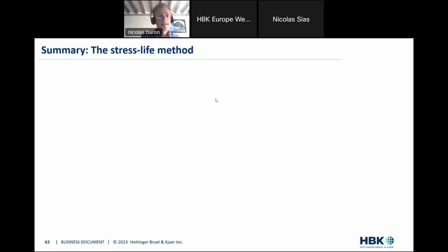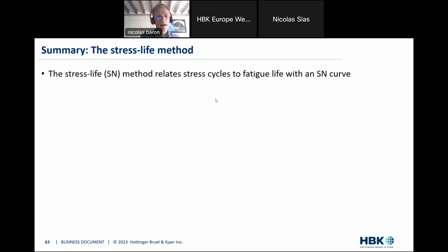To conclude on the stress life method, what is it about? The stress life method is also sometimes called SN. So again, N is the number of cycles. That's what the capital N stands for here. So the stress life method, what does it do? It relates stress cycles, remember the range of the stress values, to the fatigue life, the number of cycles you can have before reaching failure, through an SN curve. So the stress life method really is just about that. We have a given range of stress, and we want to relate that to the number of cycles that will lead to failure.